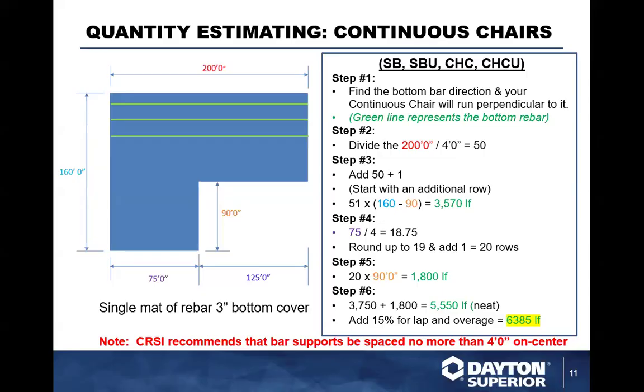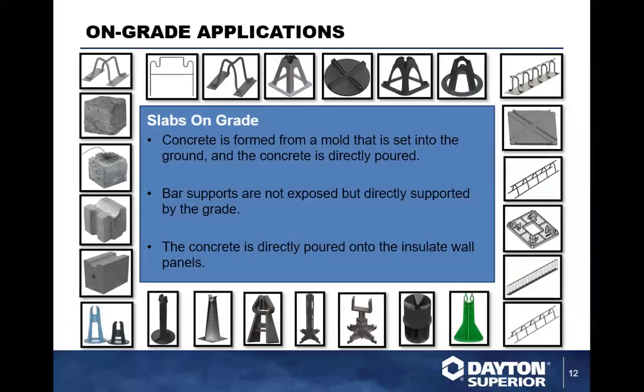So they'll upgrade a size or two of the rebar, and then that may only be a small span before they drop back down. Those are things we always need to take into consideration when we're talking bar supports and supporting the wire, wire mesh, or steel reinforcement within the slab.